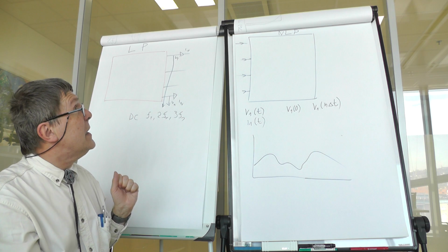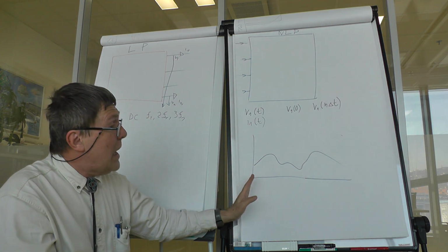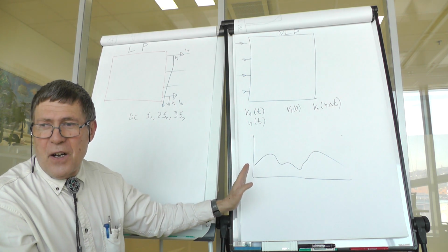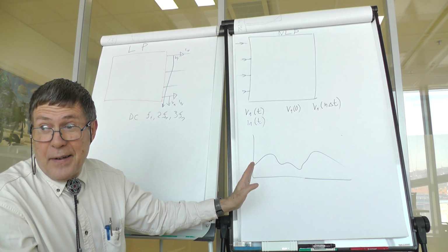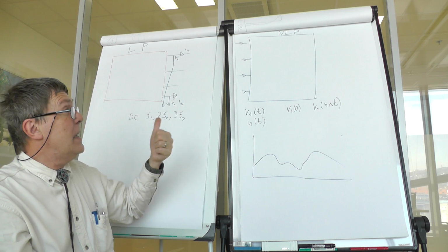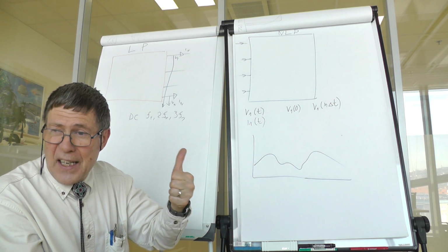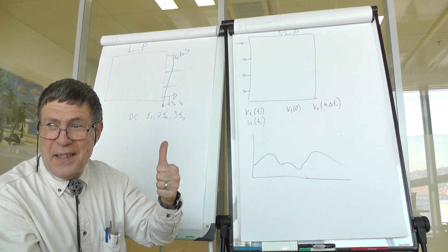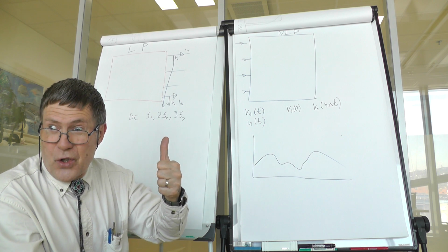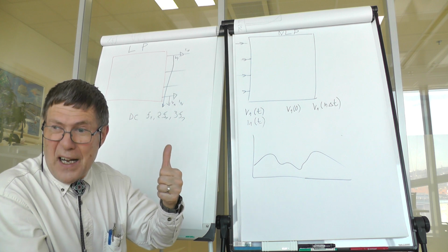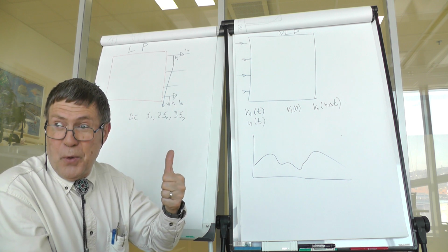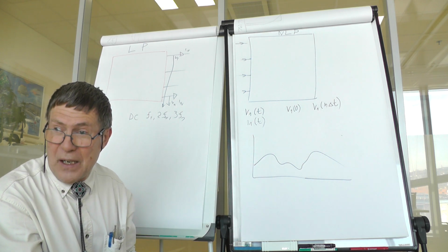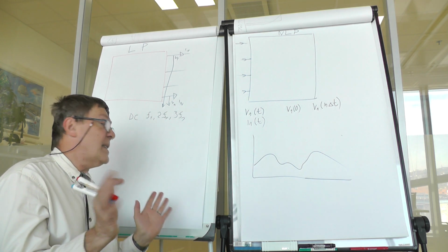So fine. It will be a nice idea for analysis of nonlinear amplifiers where you have clearly a single frequency at the input and you try to get harmonic distortion, that is mostly the third harmonic at the output, or the ratio of first and third harmonic at the output. That's simple.